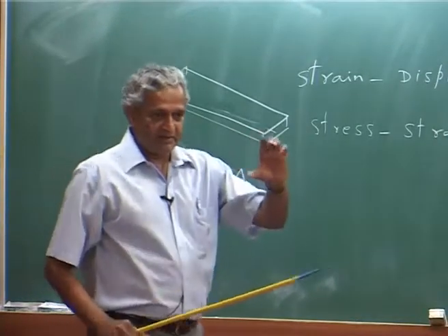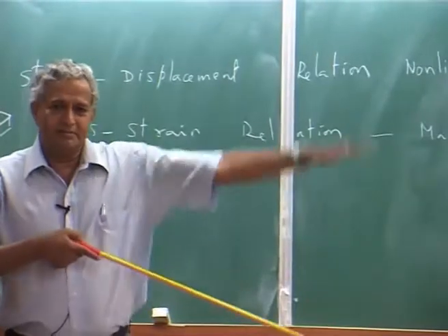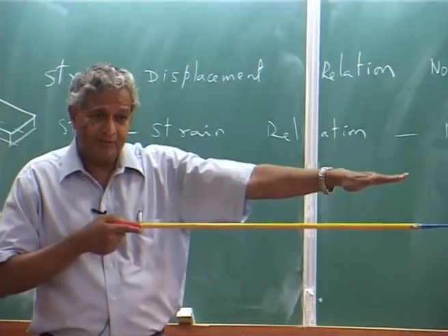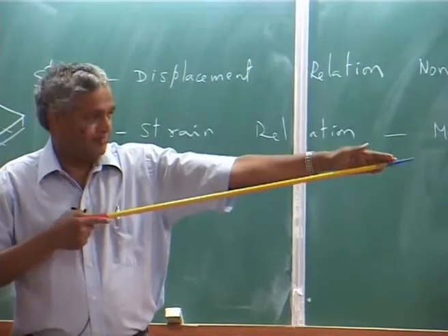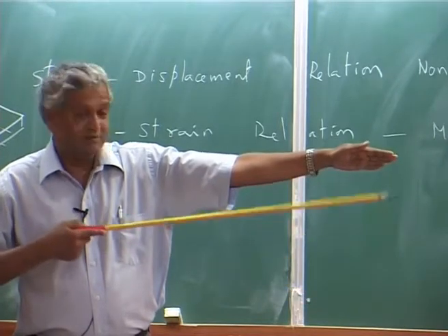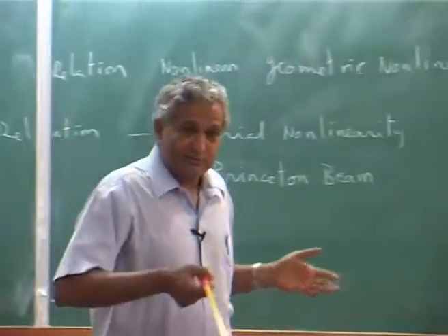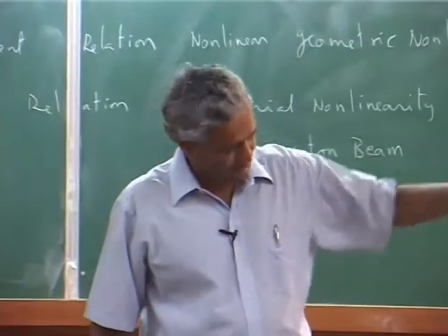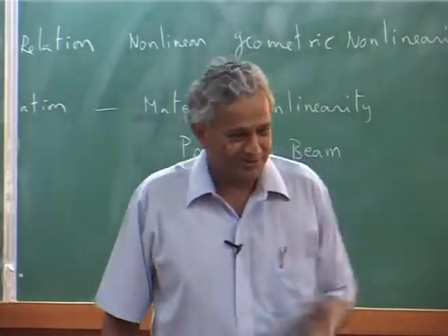If the beam cross section is flat and you apply the load, this is the beam bending. You want it to bend in both directions. So, they just took the beam, kept it a little inclined, and applied the load, which means the tip load will give deflection in the blade coordinates, in both directions. This experiment was conducted for slightly moderate deflection, large deflection you may call it.